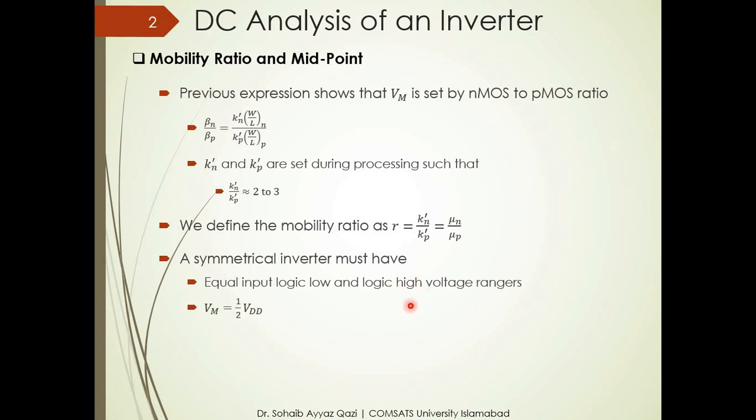It means that if we have to design an inverter which is a symmetric inverter, then its midpoint should be at half VDD, so that we have equal input logic low and equal input logic high ranges. In an example we will see how we can design a symmetric inverter and what factors we need to calculate before designing in our tools, which are Microwind, Cadence or Mentor Graphics.